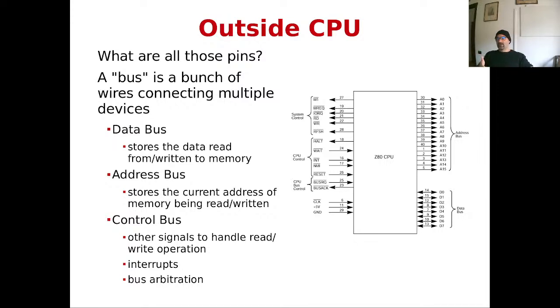In some architectures, these pins can also be put in high impedance mode, which means they can be isolated, just kind of disconnected, in case some other device wants to use the set of wires, for instance the video card that wants to read from the RAM of the PC. So in this case, the address bus can be isolated. But in general, you can think of it as a bunch of wires that output a number, a digital number.